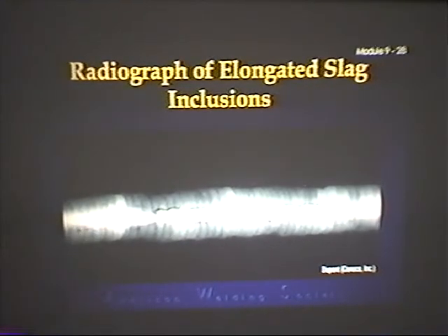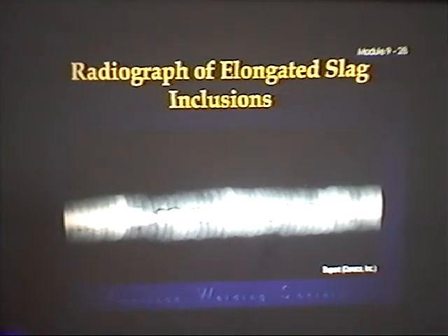An X-ray works by X-ray radiation passing through an object, and the more of the X-rays that can get through, the darker it is. The less X-rays that can get through, the lighter it remains. And so here you can tell that there's a slag or a void because there's nothing to stop the X-rays from moving through.